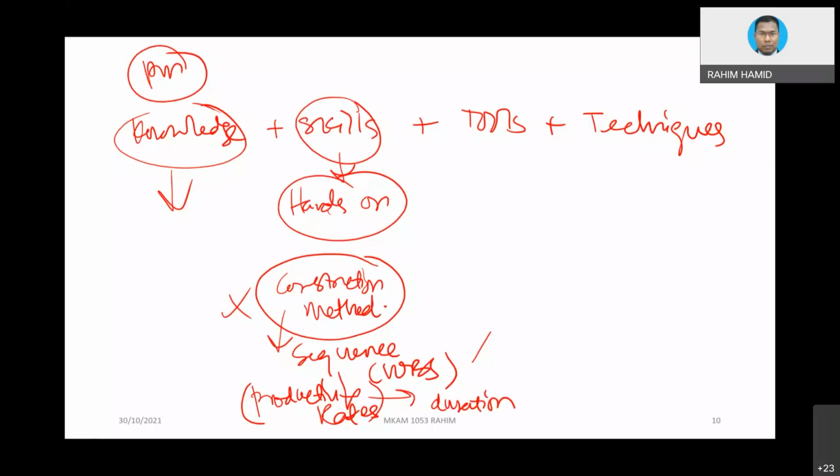And you know what? For each of the activities that we calculate, in any project scheduling you have seen, there is a basis to calculate those activities. It's not just that people simply put, okay, piling, you just put 10 days; excavation, you put 2 days. No, there is a basis for that, and it comes from productivity rate. And again, productivity rate is not put in books. In a country like the US, they do have a textbook or even a manual that they developed. But I have not seen anything developed in Malaysia yet in terms of productivity rate.